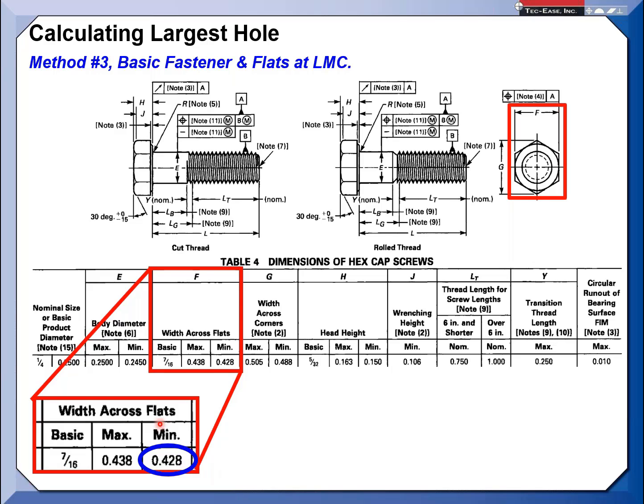And let me speak to that. If you use the 250 for the bolt, you know the bolt is going to come in smaller. The only time the bolt may come in at 250 is if it was a class 3 fit. But what winds up happening here, if you use the 250, you're actually adding a little fudge in there, or if the bolt bends a little bit, it's not perfectly a cylinder.